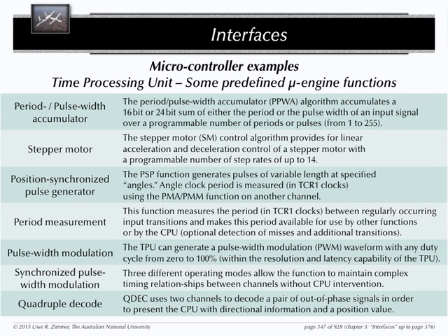Otherwise, your lights begin to wobble with the frequency of your motors, because if you actually pulse them all at the same time, this is like having your switch mode power supplies at home all synchronized, and you probably will get the whole suburb out of whack if all of a sudden all your switch mode power supplies are beginning to synchronize with each other and getting the phase of the mains shifted slowly that way. In a larger environment, if you have actually beefy electrical motors there, that becomes an obviously even more urgent issue. So you need to coordinate these kind of things.